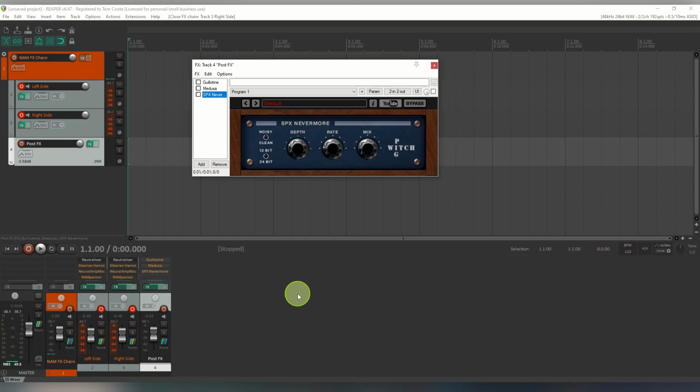What you're doing is basically halving the sample rate, so to use oversampling on something like that would be completely pointless because you're actually using fewer samples to get the sound you want, as that aliasing and that extra noise is part of what gives it its character. So oversampling isn't necessarily going to make everything sound better, and it's often quite pointless. But what is technically an oversampling based filter, which I did use, did work really well.